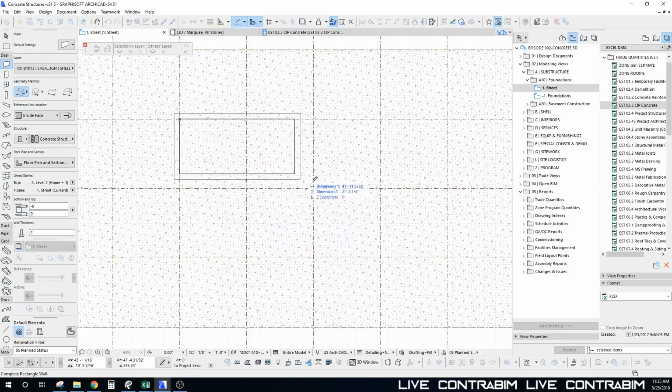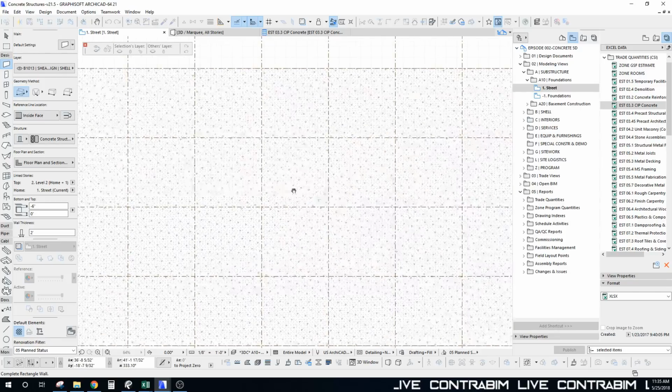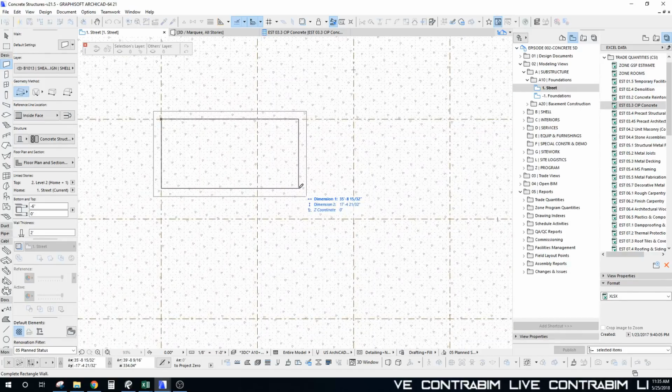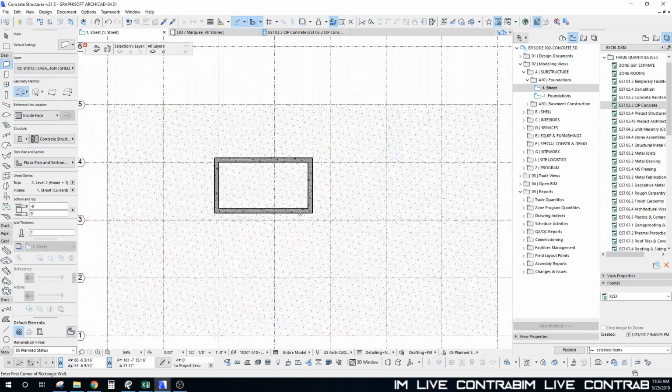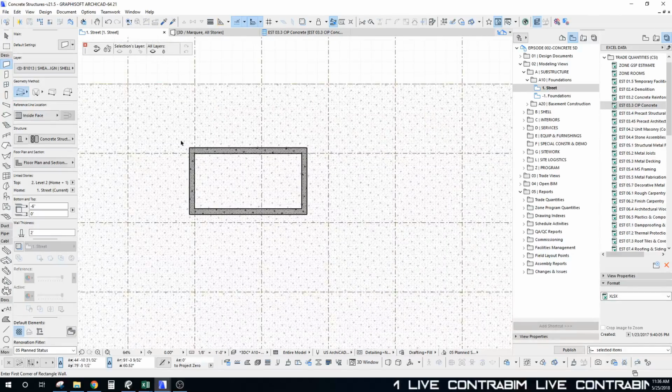And so what you're going to do here is specify an exact dimension, John. And in this case, I'm going to use, what is it that I'm doing? 40 feet for my X direction. And then my Y direction, maybe I'll do 20 feet because you could fit two elevators side by side pretty easily in 20 feet, because you typically need 9 to 10 feet in width and in depth. So it depends on the size of your elevator, or if it's a freight elevator or whatnot.